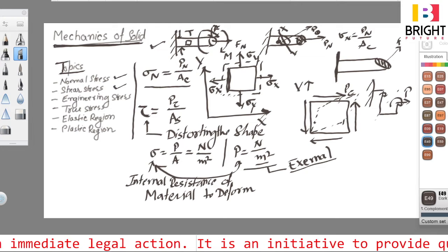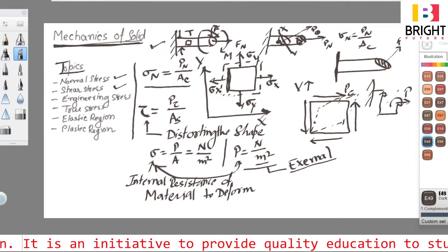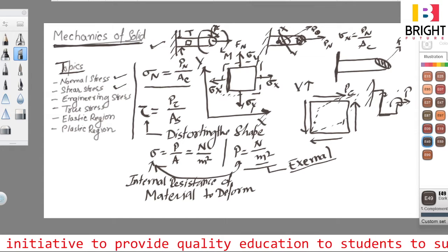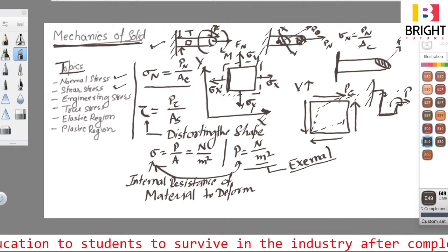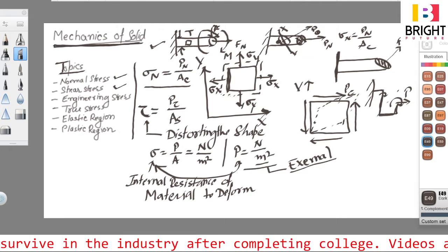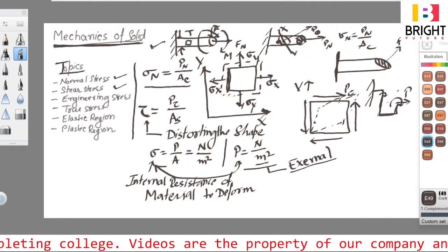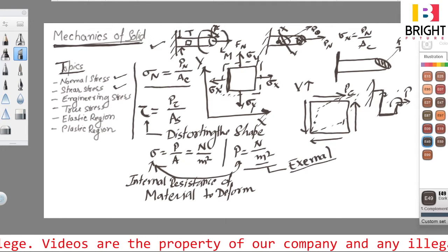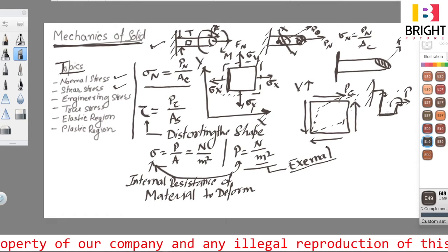This element is fixed over here. Now we want to find out what the dimensions should be for this particular section. What we will do is draw the free body diagram, then find the stress element in each of these, find the actual stresses induced in that particular component, and we will be able to find the dimensions of that particular area, right?